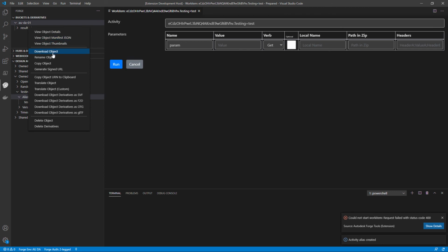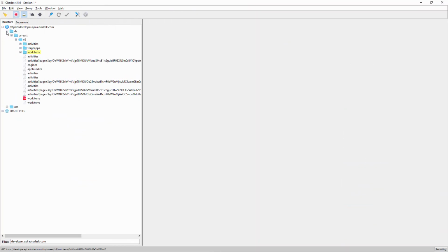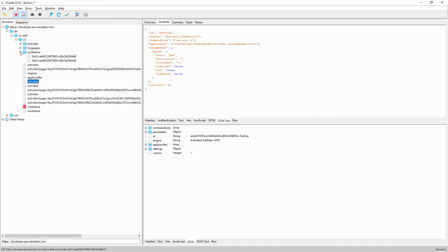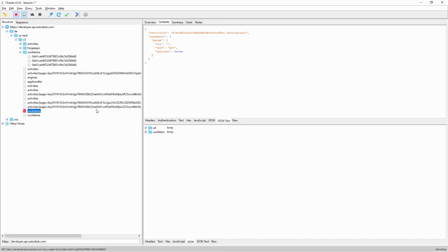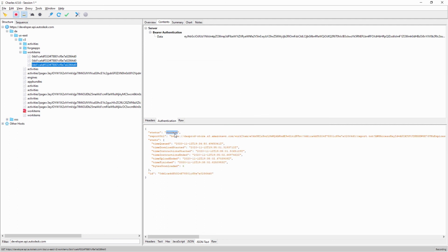When you run them before you run your Visual Studio Code, they can catch all the communication between Visual Studio Code and the Forge Design Automation servers. You can then take a look at how the communication looks, what creation belongs to what API call, the details of the call, the format of the request, and more. If you write your program and something doesn't work for you, you can compare how our tools call the API.